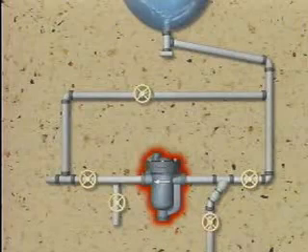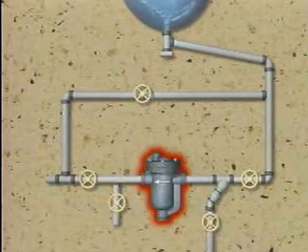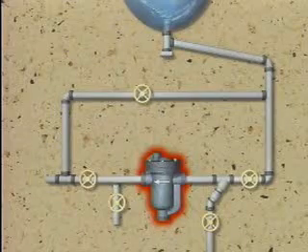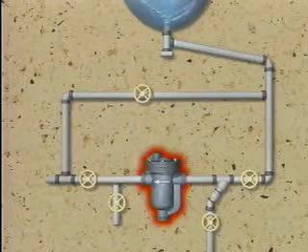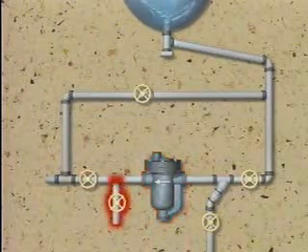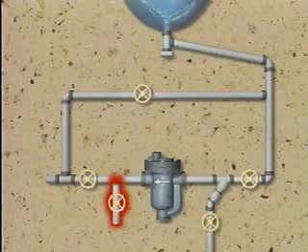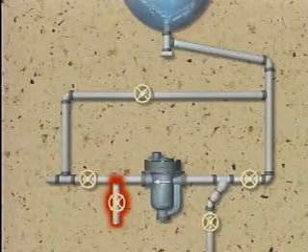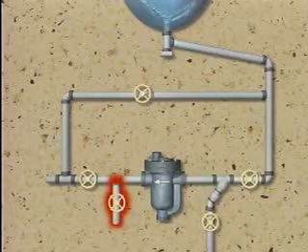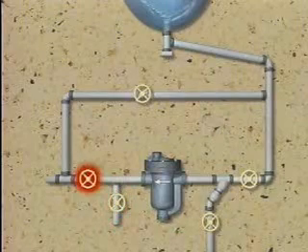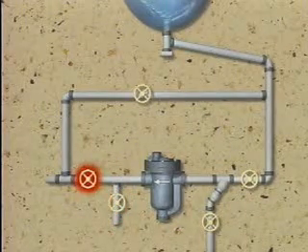The next component is the steam trap. It drains condensate from the system while preventing the escape of live steam. It may also remove non-condensable gases and some air. Downstream of the trap is a test connection with a valve. The test valve can be opened to see whether the fluid that the trap is passing is steam or condensate. An outlet valve separates the steam trap from the downstream piping.